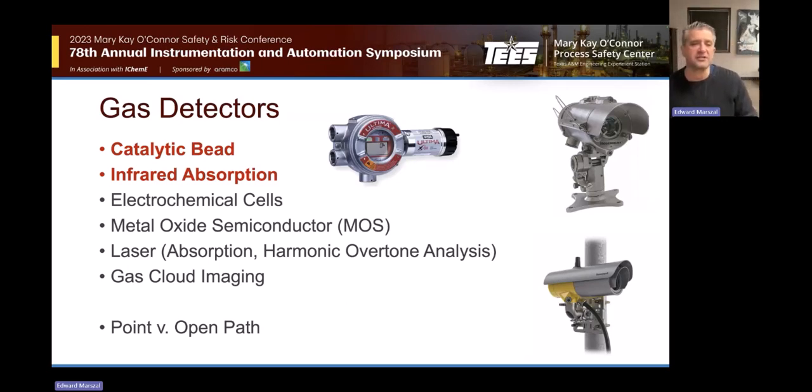Toxic gas detection, you're going to end up looking at other types of technologies that you can think about similarly in how you do the calibration and what sample gas you're using. For toxics, this whole discussion is not as relevant because for toxics, you're generally going to use a calibration gas and your target gas that are exactly the same thing.